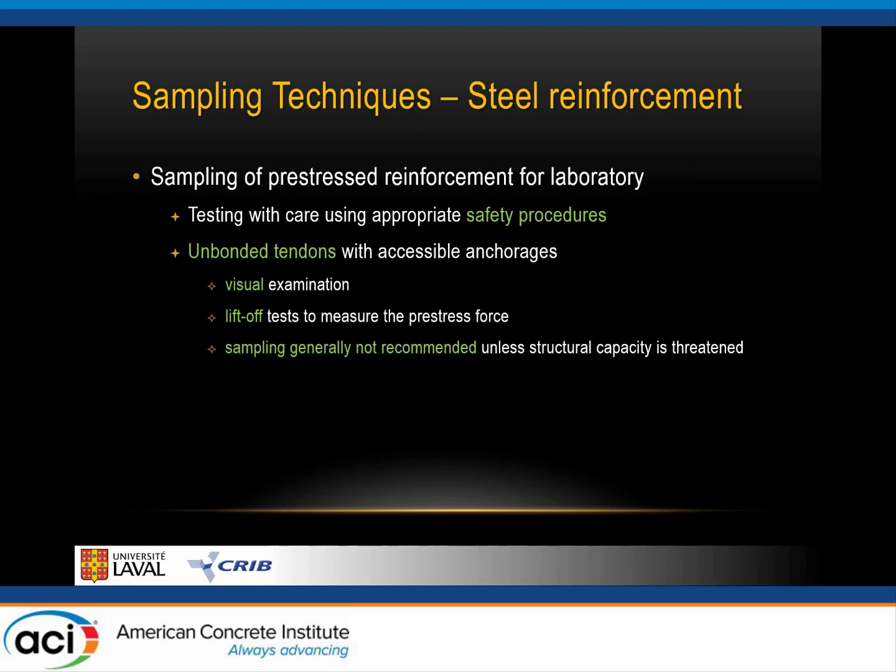When it comes to pre-stressing, it obviously needs very much care to make sure that we satisfy safety procedures. Typically we limit ourselves, in unbonded tendons, to visual exams and lift-off tests in areas where it's possible to do so when access is possible.